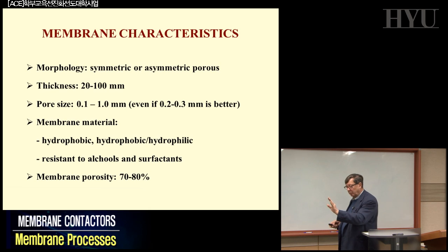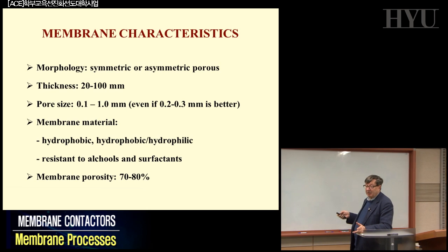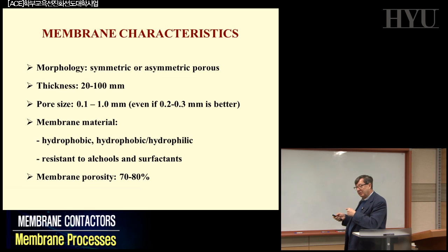You are pushing the solution to the membrane surface, you can accumulate solutes, and you create a gel layer, double layer, etc. Here you don't have this convective flux. You only evaporate, and so that minimizes traditional fouling. From this point of view, asymmetric is not really necessary, because we introduce asymmetric material also for avoiding any penetration, etc. No big trouble.